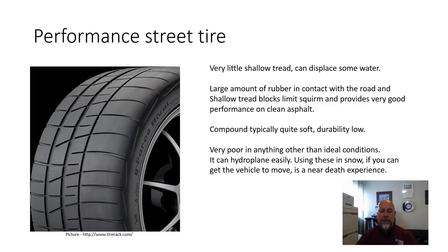Okay, so a performance street tire. These can be similar to the previous tire in the tread compound, or the rubber in the compound, but they have a lot more tread to them. So they've got tread blocks and grooves in there that will allow the tire to displace some moisture. The tread tends to be fairly short, so it's not very deep. That helps with preventing tread squirm, so you get a positive feel on the ground.